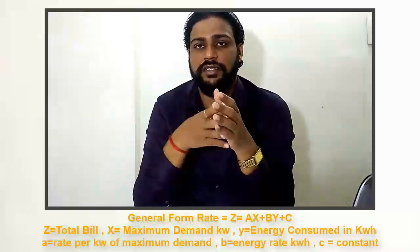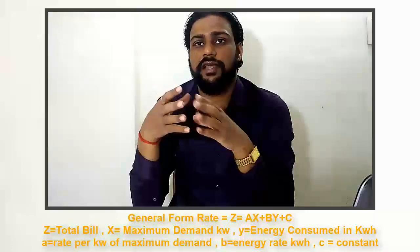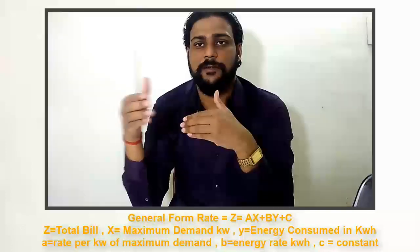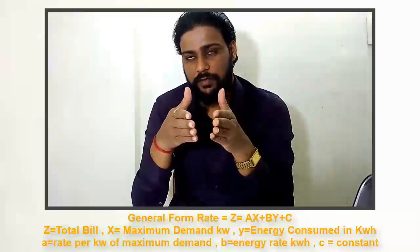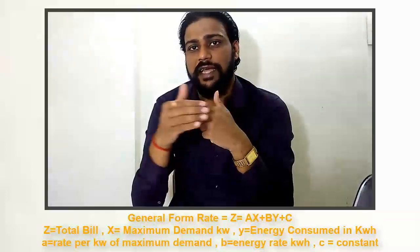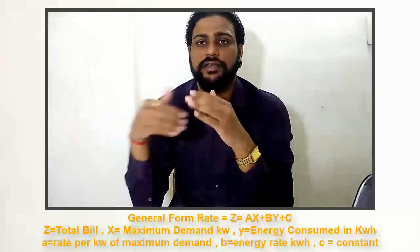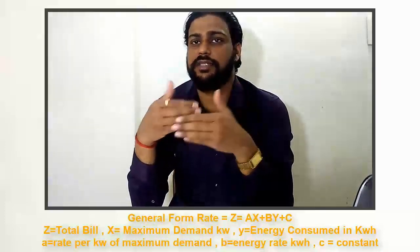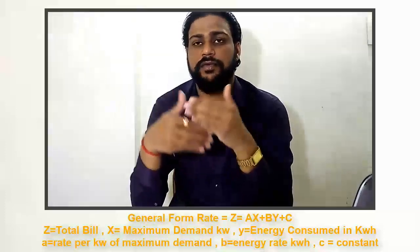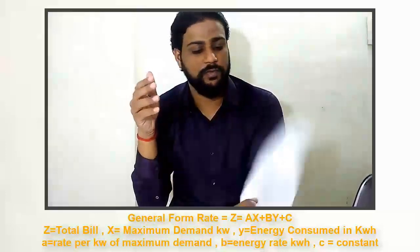So again, what we saw was that you design your power plant based on all the factors like the cost of the power plant, the fixed cost, the operating cost, and the running cost, etc. Based on these, the companies come up with an equation which helps them derive the tariff, or the amount which will be used for billing you. It will be different for different countries, and even for different states and electricity boards. They will have different rules. So this is just a general form, and the equations which different electricity boards use would be very different from what is shown here.